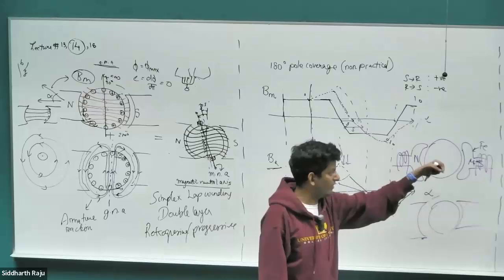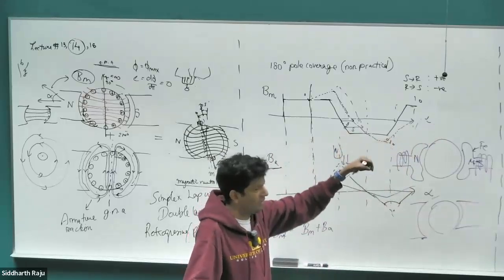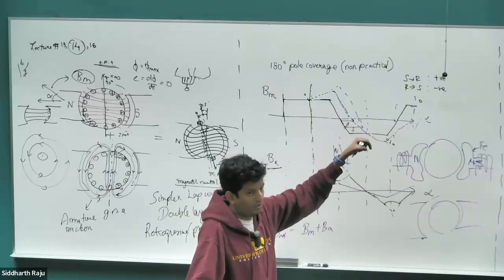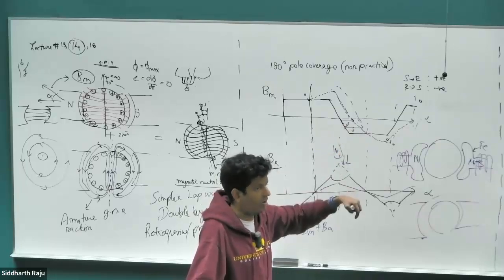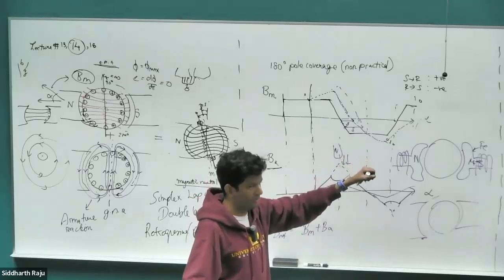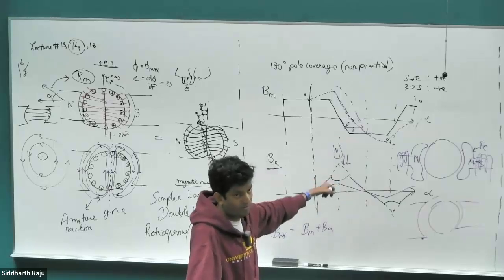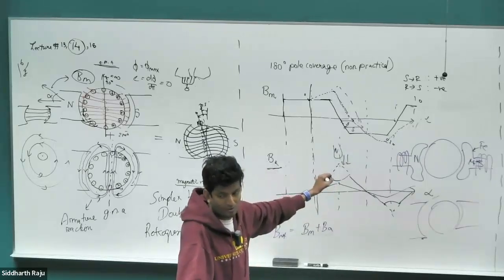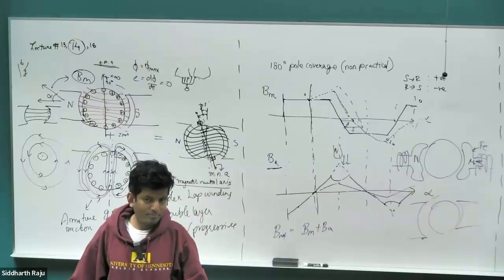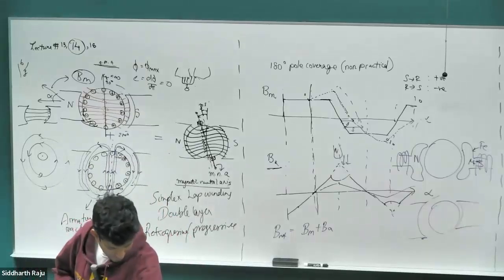And that's the reason I connected that in series with the actual rotor current that's coming out of the armature. Because if the rotor current increases, then that current would also increase in the interpoles, therefore creating a stronger magnetic field that would push it way down. If it is very low current flowing in the rotor, then the interpoles would have very low magnetic field so that it doesn't push it too hard in the other direction. Right? Very clear? Okay. So we have addressed one problem